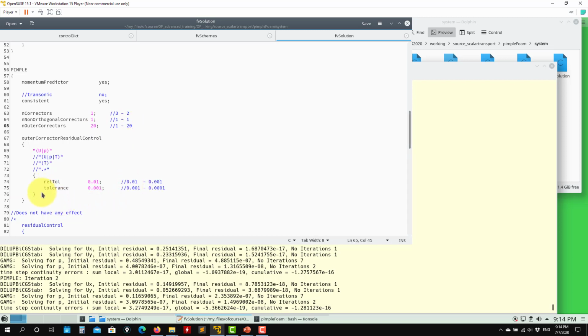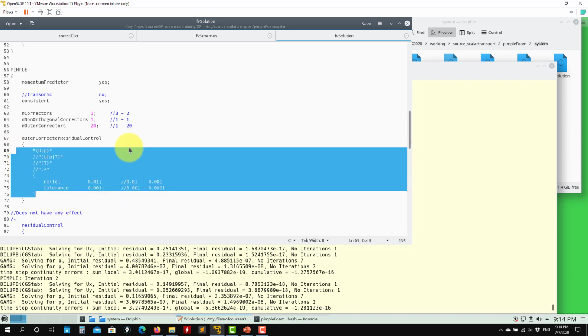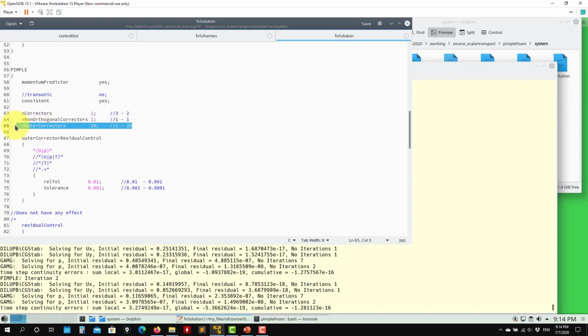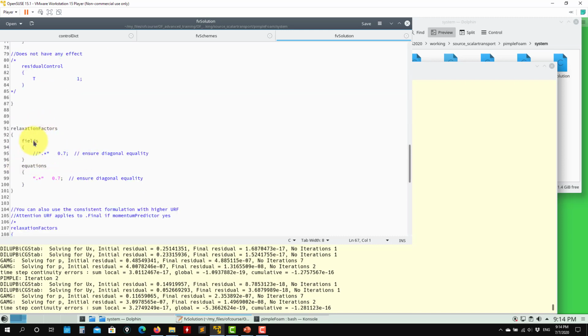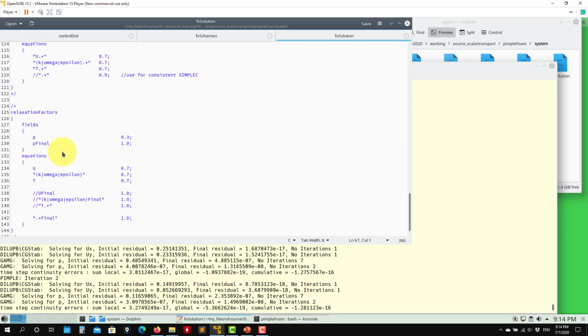Many people are interested in getting fast outcomes, and this will have a strong influence on that. Okay, but as the solution keeps going, this might accelerate and might go to 5, 4, or ideally 2 iterations. Okay, and then also play around with your relaxation, but use the industry standards, or probably 0.7 for everything is a good choice when using unsteady. For steady, we already saw that.